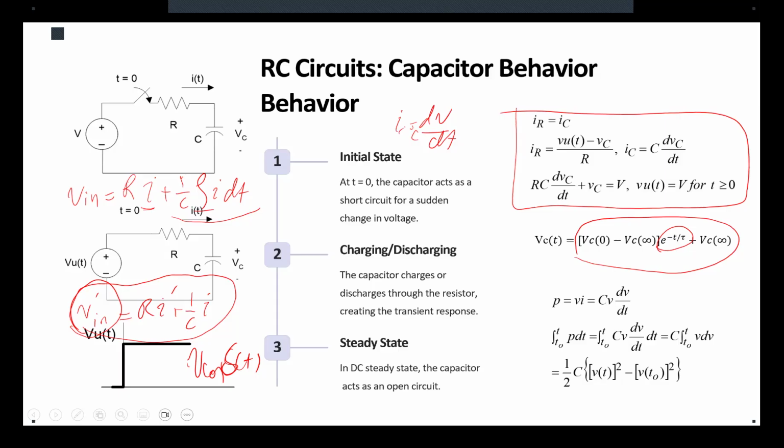So the differential of a step function is the initial condition times delta Dirac. But in our assignment the initial condition is 0. That means V prime is 0. Now, if that is 0, that means the differential of the current is minus 1 over RC times the current itself.